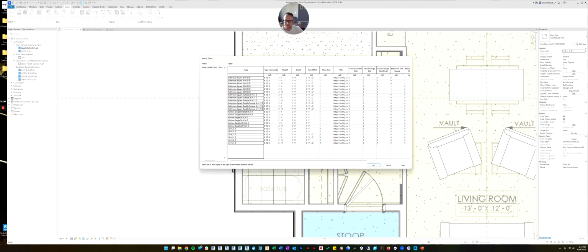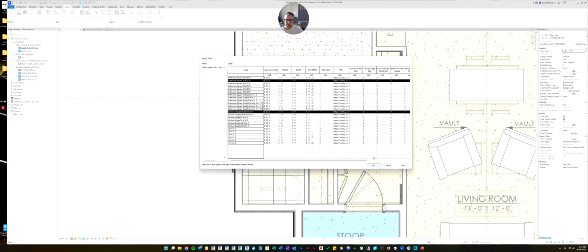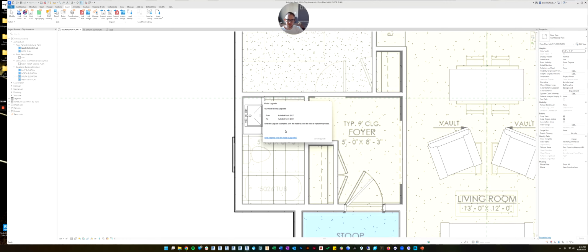And this time, maybe you also want the round option, 36 by 21. And maybe you also want a kitchen. So 36 by 24. But you don't want the small one. Let's do that one. And then if you control click, you can select what you want. So we want a double sink, 36 high by 24 deep. So again, it'll convert those and bring them in.